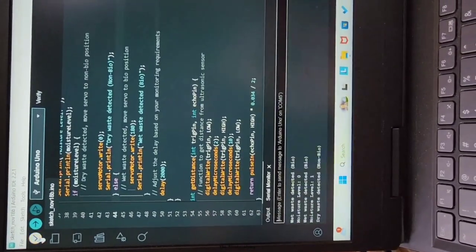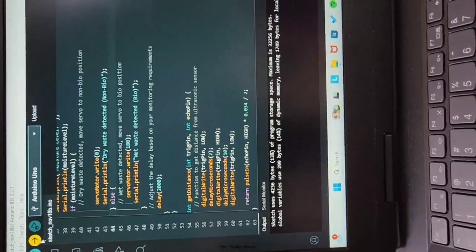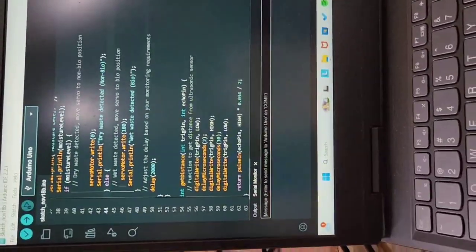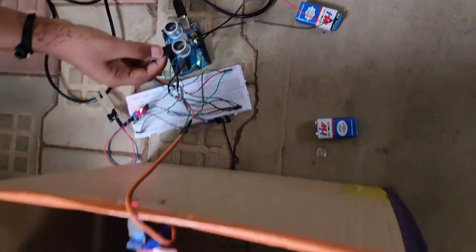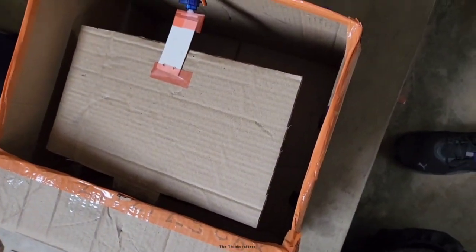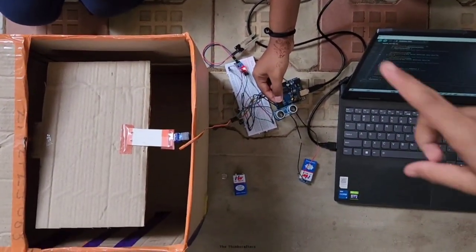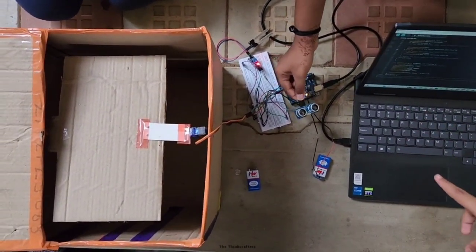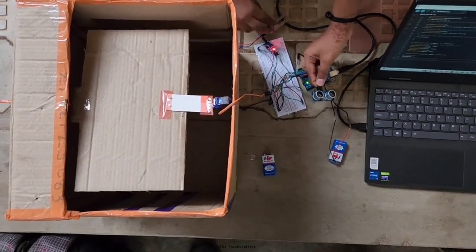The servo motor receives electrical signals from the Arduino through pin number 12, allowing it to rotate precisely to angles like 0 or 180 degrees. This movement controls the bin compartment's tilting, aiding efficient waste segregation. Meanwhile, the ultrasonic sensor operates by emitting waves through pin number 9 and measuring their echo at pin number 8. By calculating the echo's return time, it gauges the distance between the sensor and waste, crucial for activating the bin's tilting mechanism based on the waste type detected.